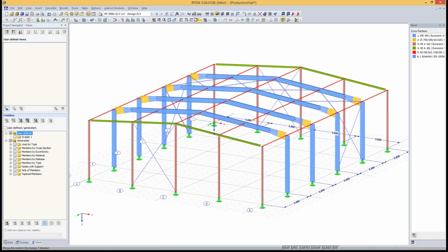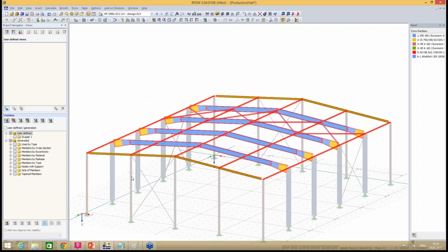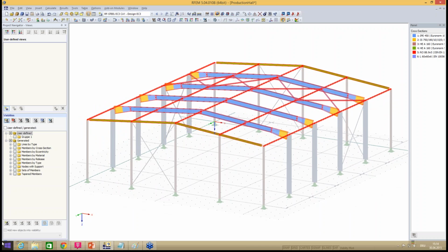So what I want to do is change to the view in the -y direction, and I select the upper belts. And now I want to only display the selected objects. So I do a visibility by selected objects. And now you see that you still see the rest hidden in the background, so they have not completely disappeared. It looks like this in the isometric view.